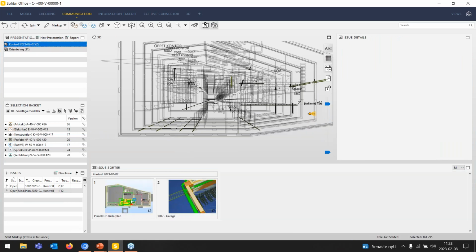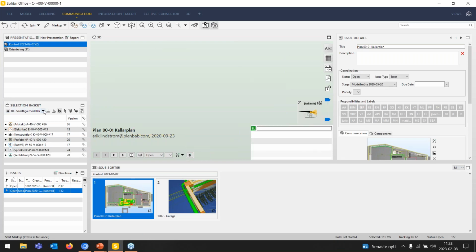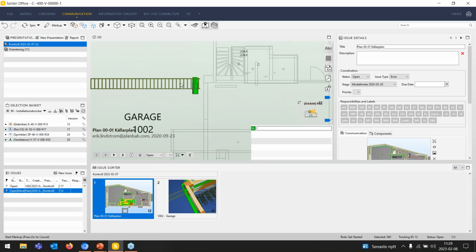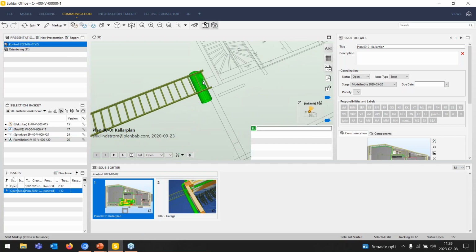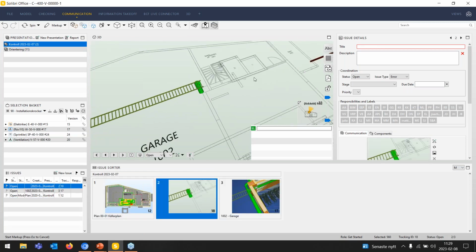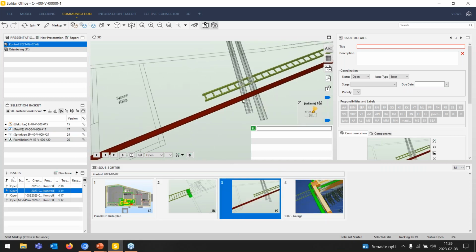and then I make, here I have for one floor, so I can switch between all the models and just the collisions that I want to look at. And from here we can see, for example, I have uploaded some older models, so we can actually see some collisions. And here, for example, we had this collision between the cable carrier and the ventilation duct. And then for all the issues, I create new slides and choose which one I want to talk about in the meeting.